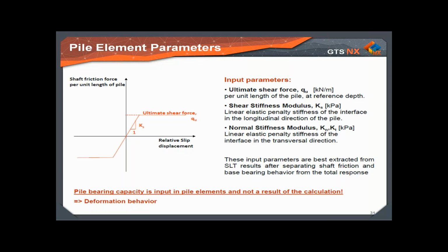This ultimate shear force you need to get from a pile loading test, if you have one. From the curve, you can separate the shaft friction from the base, and the base from the total load-deformation behavior, and assess your ultimate shear force for skin friction.